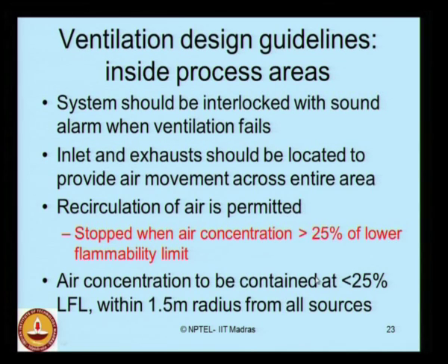In case any such process in the area fails the ventilation guidelines, then control of fire or combustion reaction can be possible within a short span of time. So, two conditions exclusively are required for inside process areas. Air concentration should be lower than 25% of the lower flammability limit of the fuel, and the air concentration should lie within 1.5 meter radius from all possible sources of ignition.